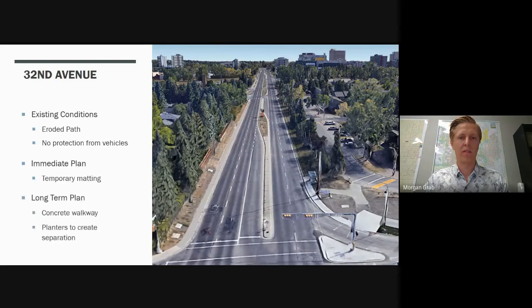For the long-term plan for this area, we propose a concrete walkway be constructed with concrete planters along the road, and to add this to the City of Calgary's snow clearing plan. The planters serve to create separation from the roadway, which increases the perceived safety of the pedestrian, and to beautify the area. These changes correlate to a decrease in dollar value of the trip cost from $12.63 to $9.86, all the way down to $5.11 for the final plan.